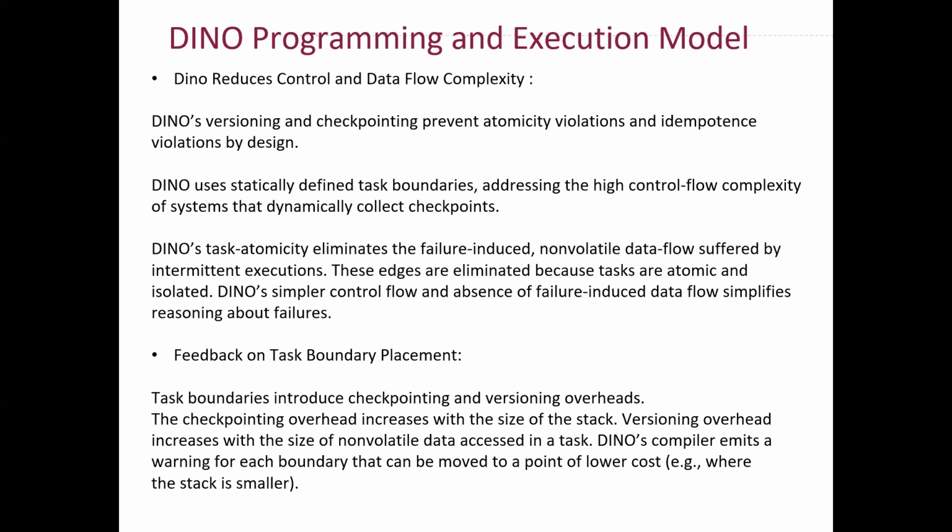In that sense, a key advantage of DINO is that the target of each failure-induced control flow edge is statically known. So you know when the program is going to lose power, and you place the task boundary as per when you know that the model is going to lose power.